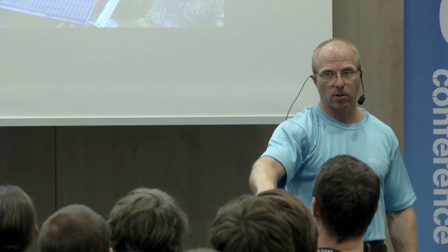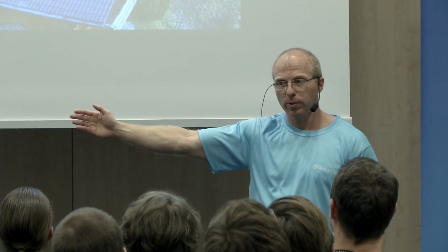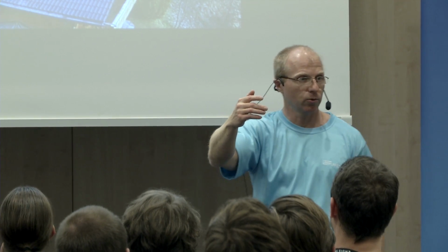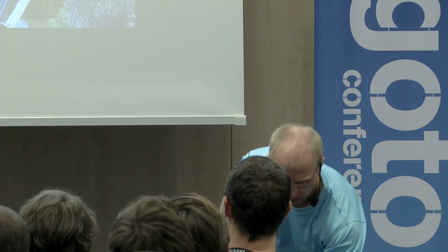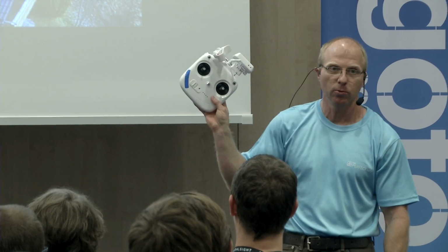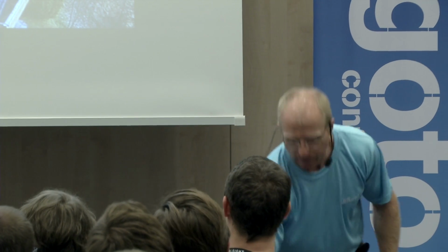And when this drone takes off, it notes the position. That is the home position. So if at some point the battery level gets low or the drone gets out of reach, it will return to home, to where it took off. I tried that. It's pretty simple to do. I just turn off the remote controller, then it loses signal and it comes home. And guess what? It landed on the exact same spot as where it took off.